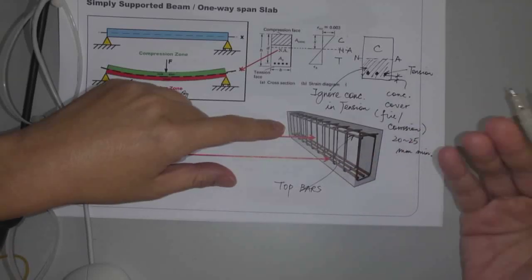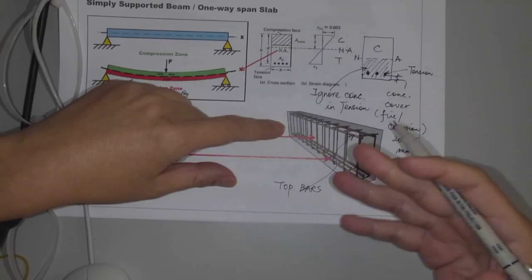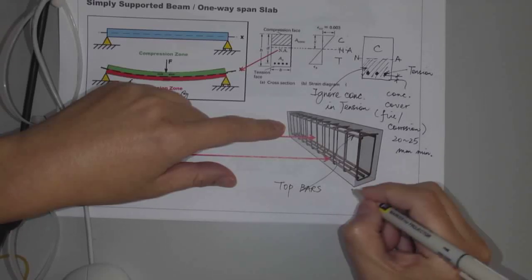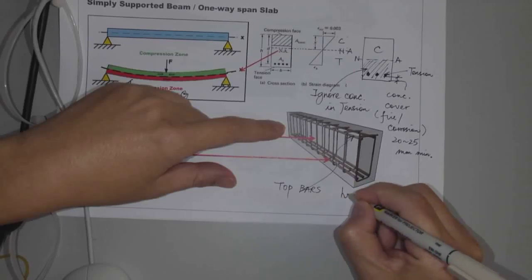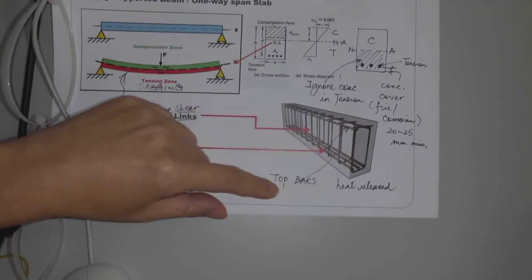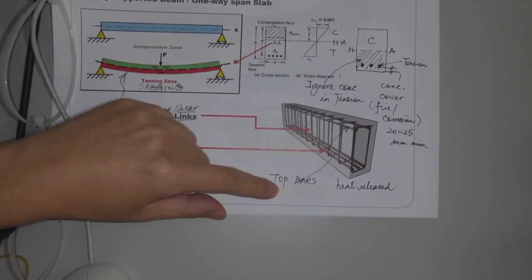And during the hardening, what happened to the concrete? That's something you should have done in your material part. What happened to the concrete when it hardens? Two things happening. Of course, there's a lot of chemical reaction undergoing. So what happened when the concrete hardens? Two major things. First, heat release. 有熱能產生. That's something you should know. When it hardens, heat is released. Right, when concrete hardens, or the hardening stage, the heat will release.